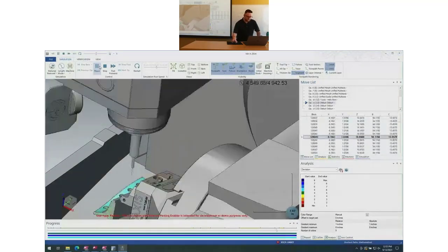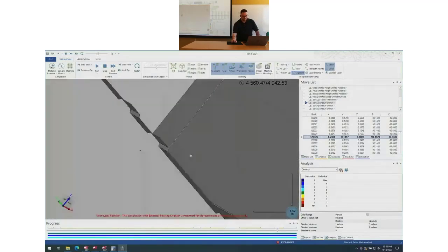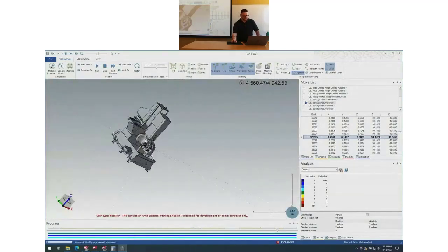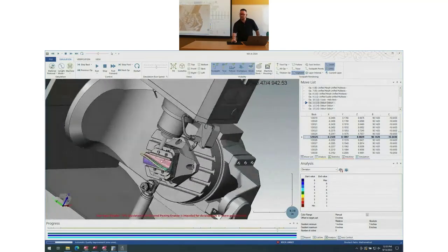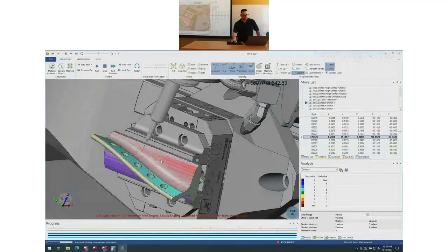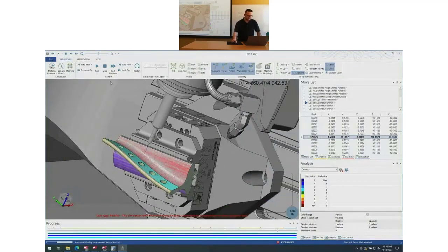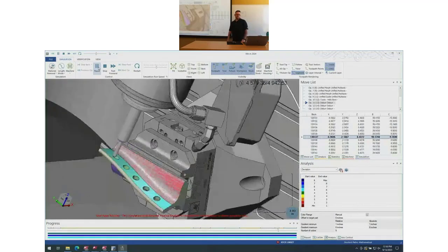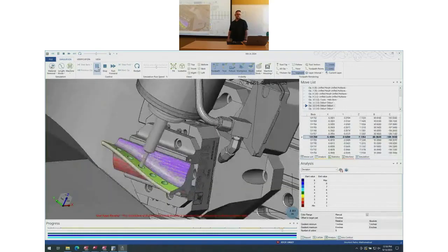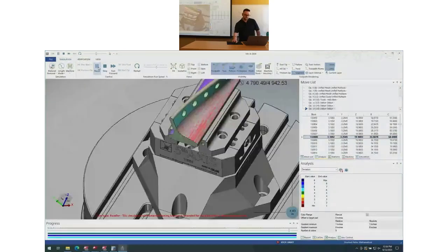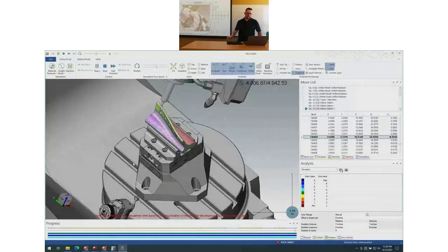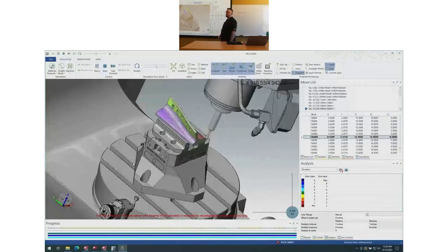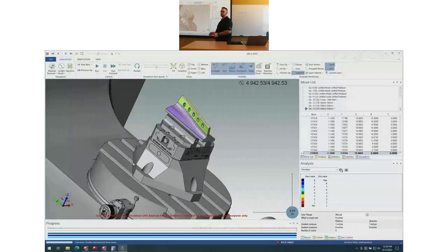So here, let's get a better angle on this. Whoa. I missed my 3D controller. There we go. You get used to it. It's hard to not have one. So here, we're using a chamfer mill to do just general purpose deburring on kind of any edge we want. And it's whipping around a little bit here. But using a common tool that most people have laying around rather than something fancy like some lollipop tool that you're going to use twice, right? It's nice.